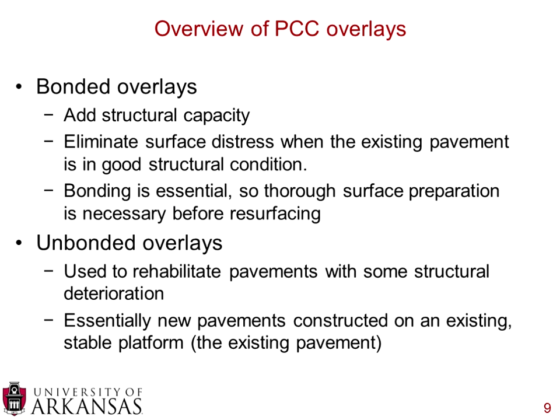So when you're thinking about a general overlay, these bonded overlays add some structural capacity. You can eliminate any sort of surface distresses, again, when the existing pavement is in good structural condition. So if you feel like you have a pavement in good structural condition, you can simply place an overlay on top of that, and you don't need to worry about taking care of those surface distresses with any sort of rigor.